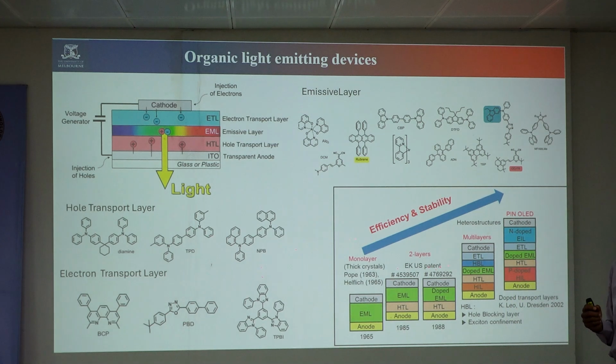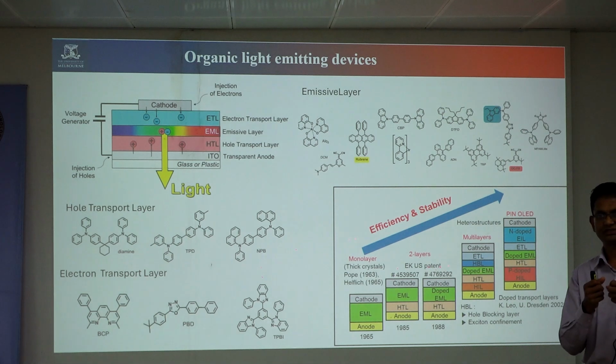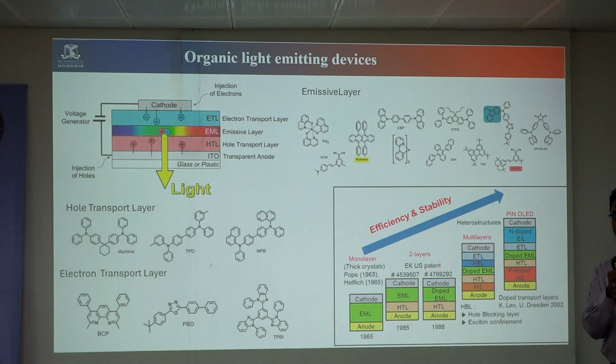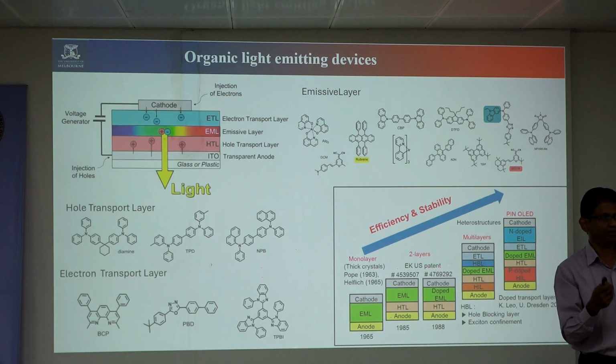They are doping. We know that in silicon also we do the doping, because intrinsic silicon is not conducting. We specifically inject impurities inside. For example, for P-type we inject boron, because boron has only 3 valence electrons, so 1 electron becomes a vacancy. For creating N-type silicon, we inject phosphorus, okay? Silicon has 4 electrons, phosphorus has 5. Out of 5, the 4 are bonded with the silicon, and the remaining one is free. So we can have 1 free electron for 1 phosphorus. Like this we can create N-type or P-type material, okay?